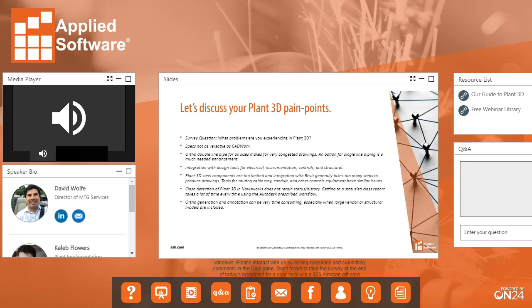As far as the isometrics are concerned, P3D does handle that very differently. It's a lot of XML configuration, which, if you're familiar with the legacy configuration of Isogen in the past, was not fun. Isogen has since moved on to a new, more user-friendly interface. I wouldn't go so far as to say it's great, but it's definitely a step in the right direction.